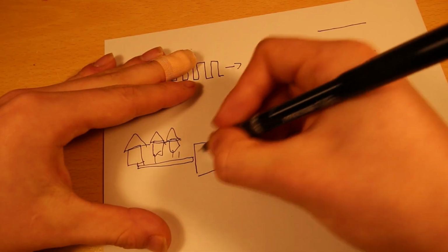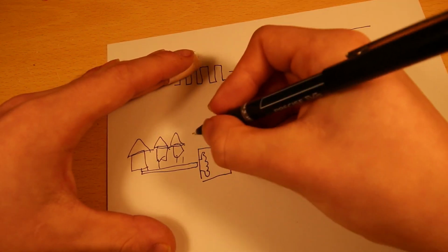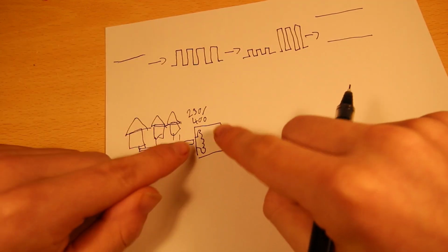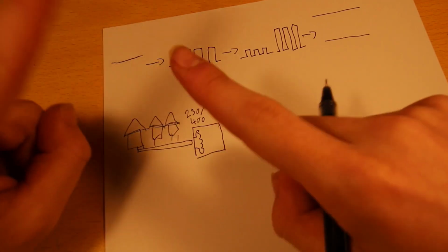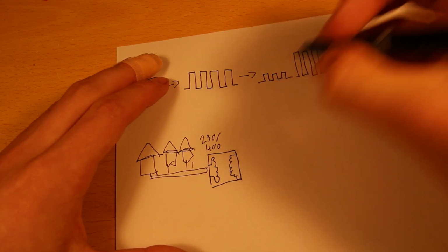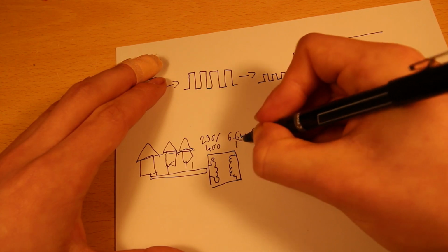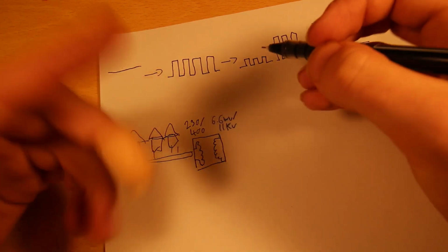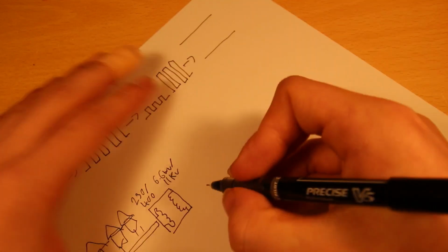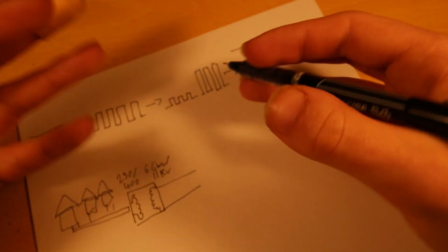So in this case, for me, where I am in Europe, the secondary winding here, so this is one coil of wire, the secondary winding will output 230 volts / 400 volts. I will then explain why there's two voltages here. Again, AC is weird, I did warn you about this. On the other side, there is a winding here, which is 6.6 kV / 11 kV, which is 6,600 or 11,000 volts. Again, I'll explain why two voltages in a minute. Those wires then run, there'll be wires that run back to another even bigger substation.